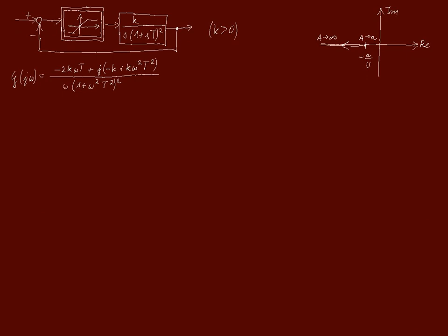We should also know what the Nyquist plot of this linear object looks like. It has integration, so it starts at -infinity, and the two inertias tell us that the graph is in two quadrants of the coordinate system.